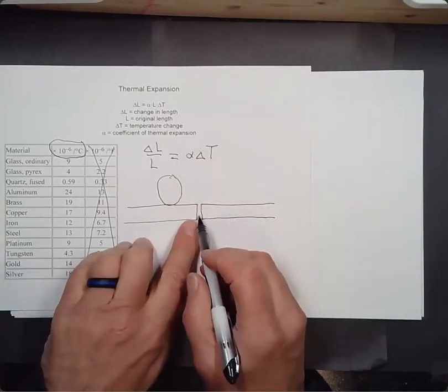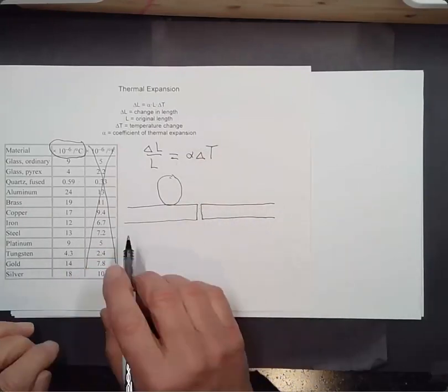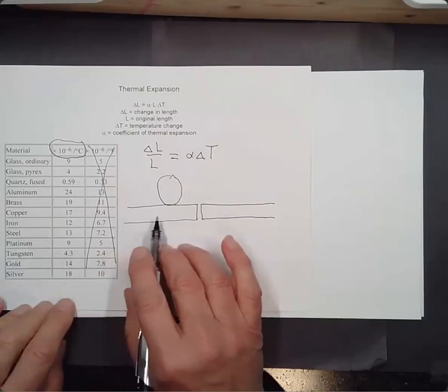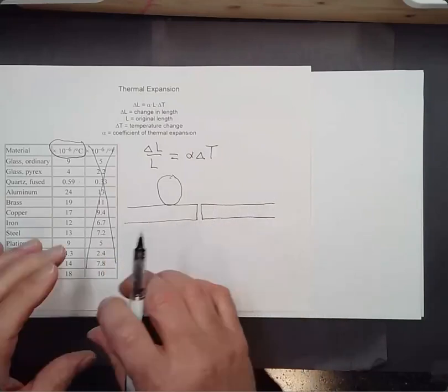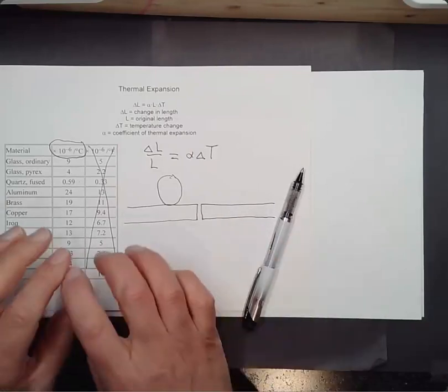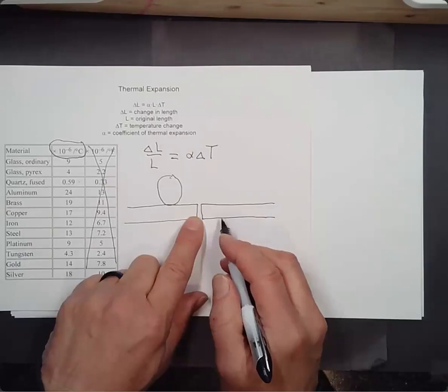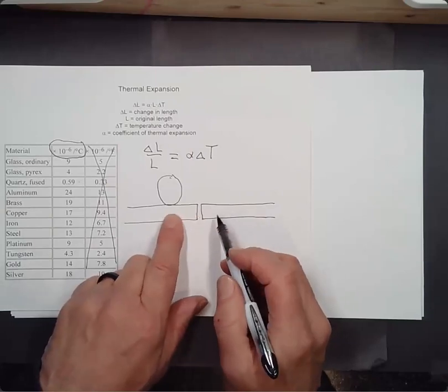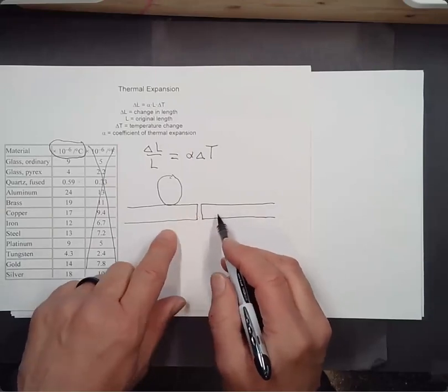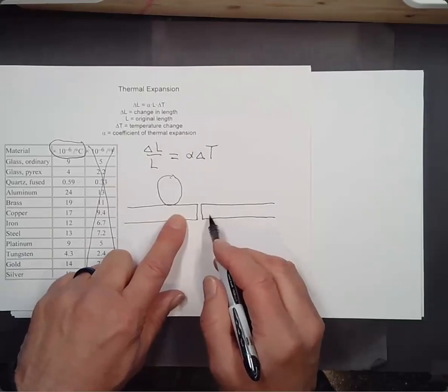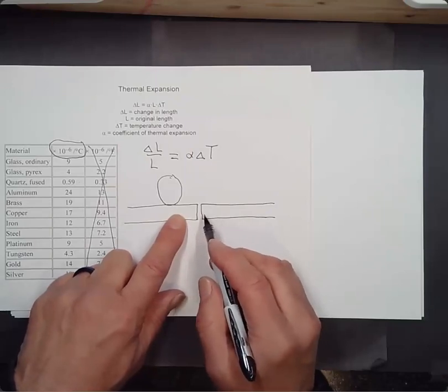Nowadays, they use continuously welded rail. They start with very long sections of rail, and as they lay them, they weld adjacent lengths of rail together. They would still want to expand, but they fasten them down much more thoroughly nowadays than they used to.